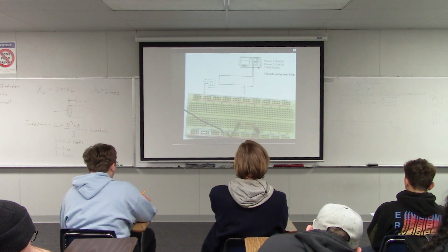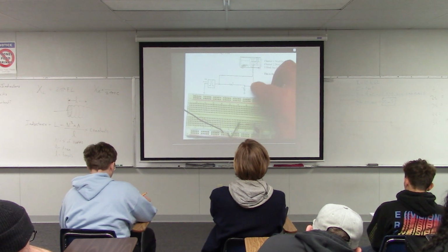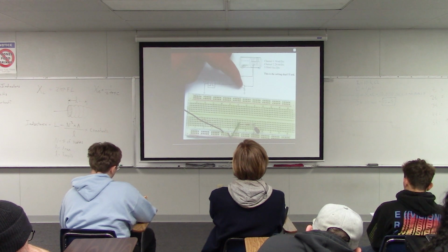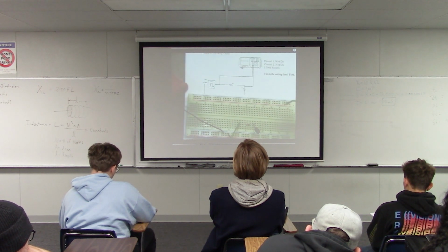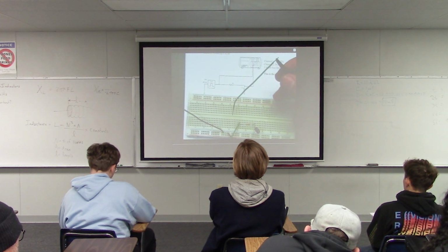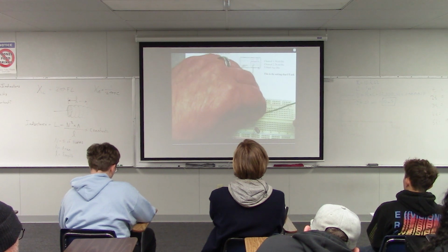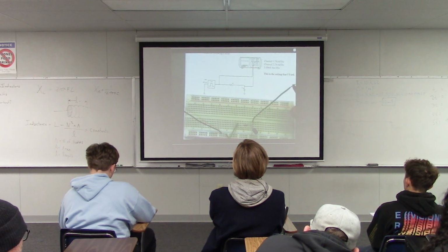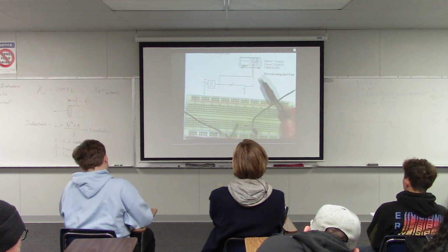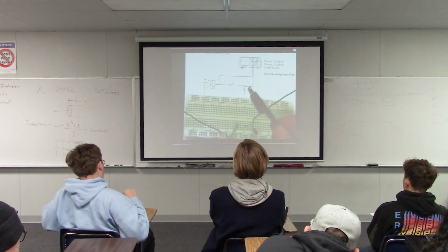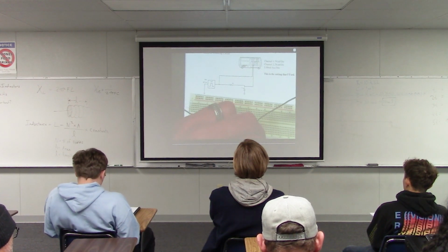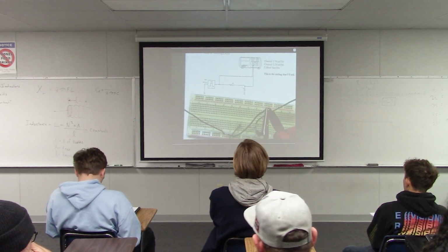And then the other lead of my oscilloscope is going to this point right where the capacitor connects to the resistor. So I'm going to take this other lead from my oscilloscope. Again, it's connected to a jumper wire, and I'm going to push that right into this spot where the resistor meets the capacitor. So I've made that connection there. And then I'm going to take the ground clip from this oscilloscope lead, and I'm going to clip that onto the ground down here as well.